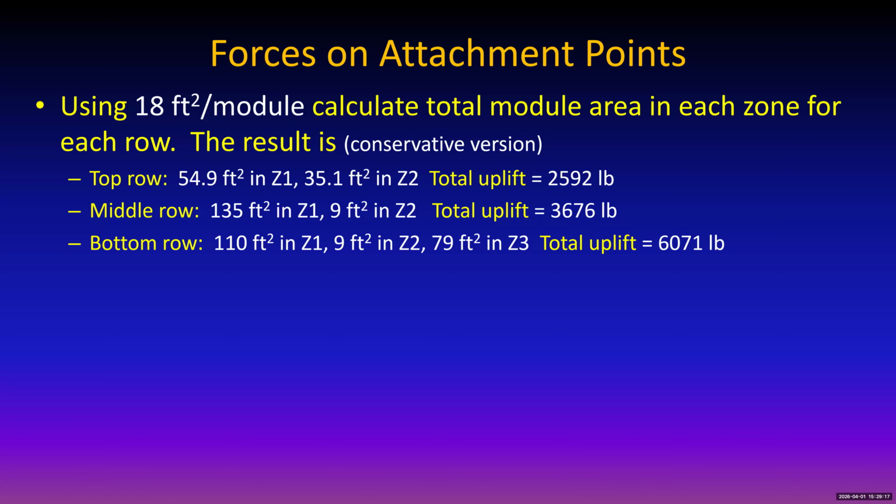Well, if you use a 5/16 lag screw, that's the most common type used. Sometimes a 1/4 inch is used, but most commonly it's a 5/16 inch stainless steel screw, somewhere between 3 and 4 inches long. How far does it have to go into the truss?